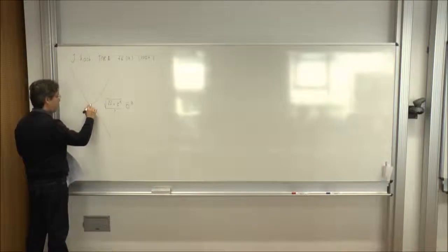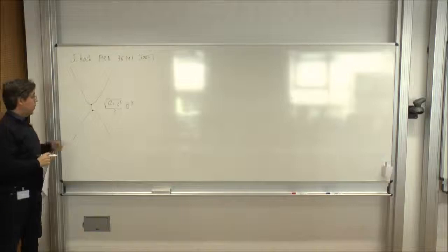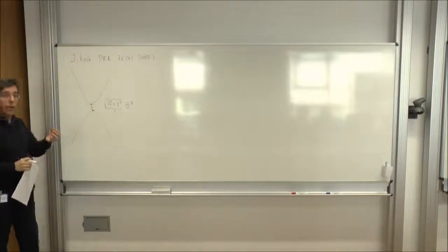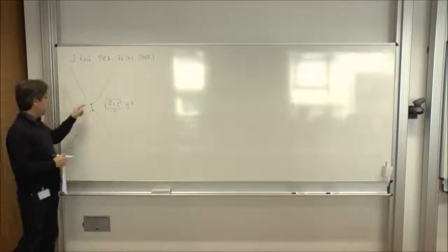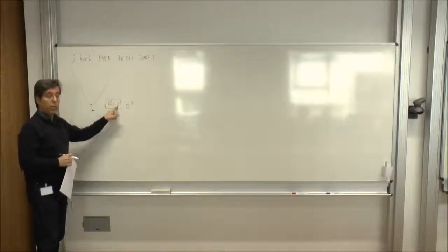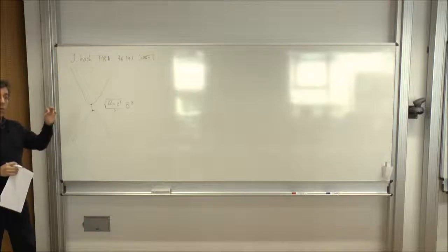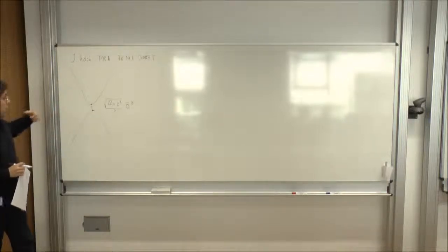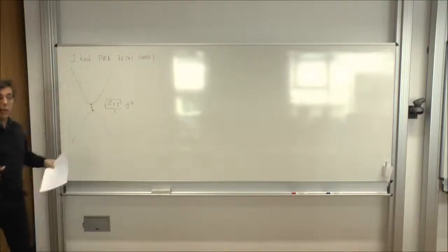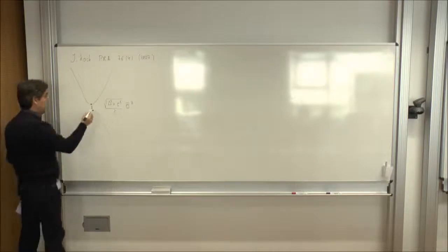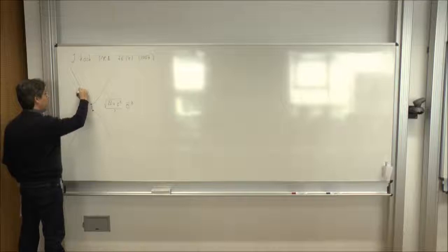And typically, experiments operate best around this symmetry point because it's the point where the energies of the system are least sensitive to external fluctuations. So basically, epsilon is an external voltage. This voltage can be caused by your electrodes, or it can be caused by surrounding charges that could be trapped in your dielectric or anything. So you expect that there is going to be noise in all these terms.